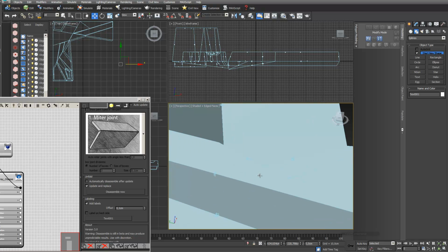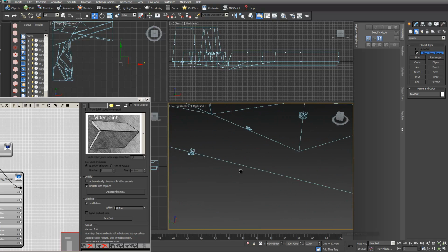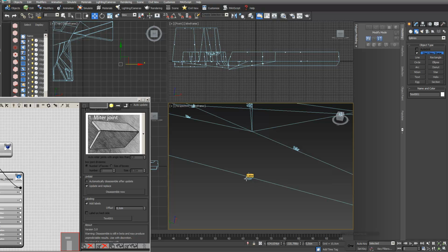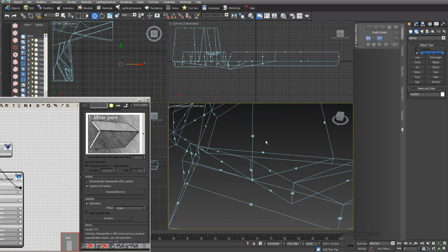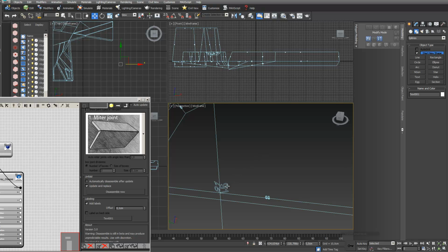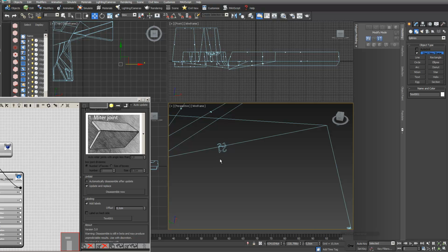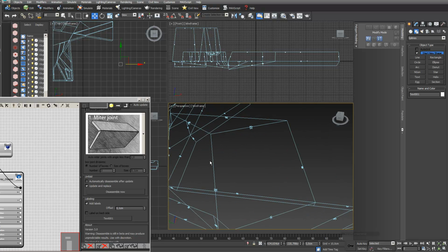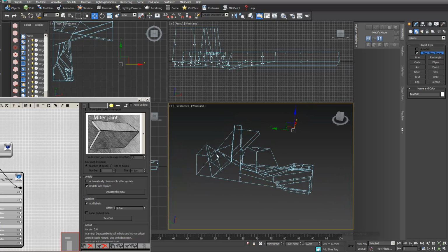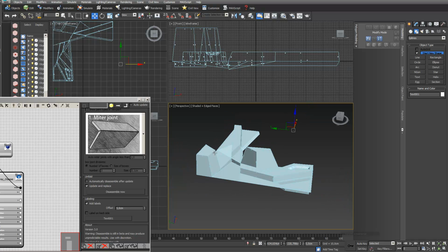And you can see, if I go into my setting, that these numbers are connected. 42 is connected with 42, and here it's like 91 to 91. So you have a good chance to be able to assemble this. If it's too close to the corners, which it looks a little bit like because of my scale, just enter like 5 centimeters, and I go again into disassemble. And this already looks much better. There's a bigger distance to my edges. Okay, I go again F3 and shade it.